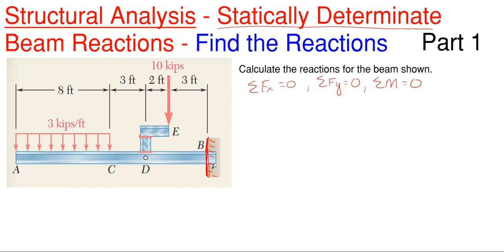Now, in real life analysis, you would have to double check or even triple check to make sure that the surface, that wall, that ground, whatever that beam is sticking into, is strong enough and capable enough to actually turn that into a fixed reaction point. But here we're just going to safely assume that it is a fixed reaction point because, well, there's no other reaction point anywhere else. So with a fixed cantilevered reaction here, we're going to have 3 reactions occurring at this point.